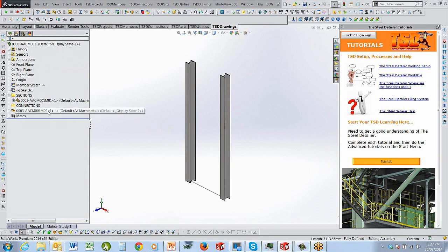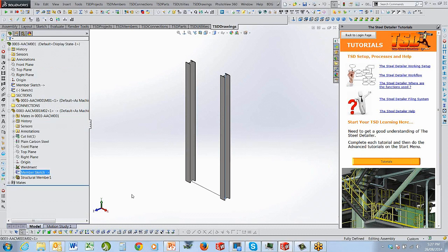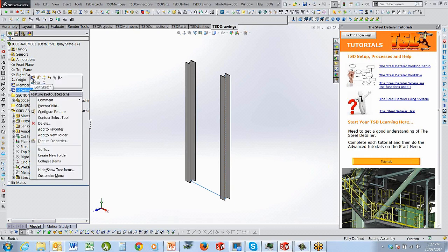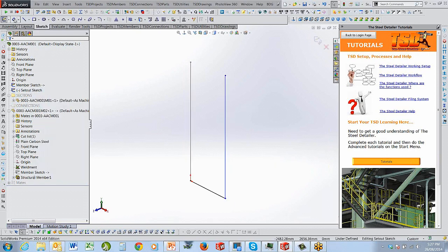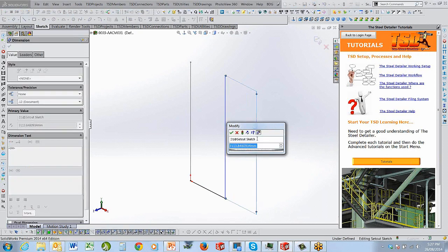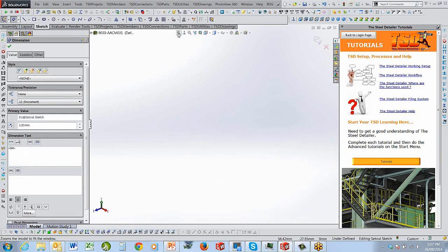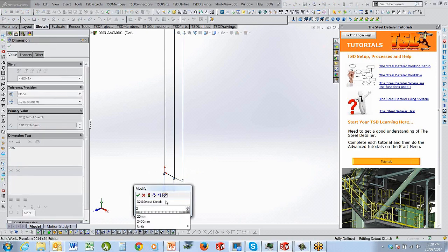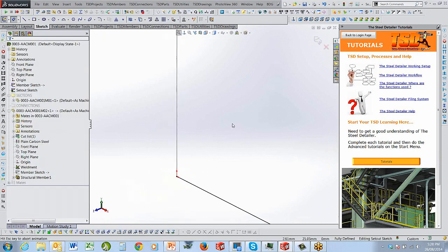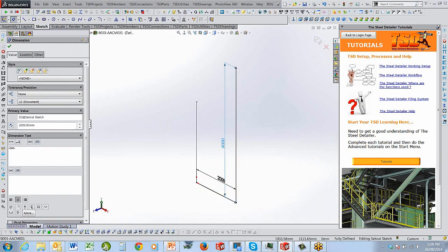You'll now notice that when I go to insert that component, it's automatically added the relationship. And my sketch here, I can go set out sketch and give that a name and put some dimensions on this thing so that it's fixed. And SolidWorks likes to, what's that done? Shrunk it right down. Yep, 5 meters. Silly bugger. And 2 meters. And that'll pull it back out again where I wanted it.